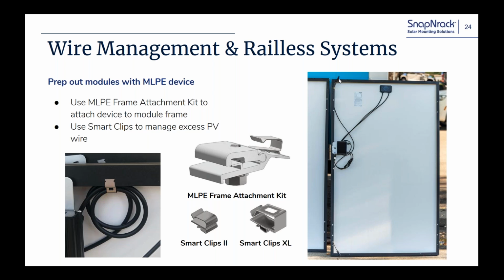And you can see here they've got the MC4 heads positioned so that when this module is lowered, this side right here is lowered into the mounts, and then they lower the module flush to the roof. They can just clip it right into the next module. If there's any kind of sagging, again, they can just kind of tug on this a little bit, or if they need to, they can add a couple more clips. But it's very straightforward, makes the install very fast.